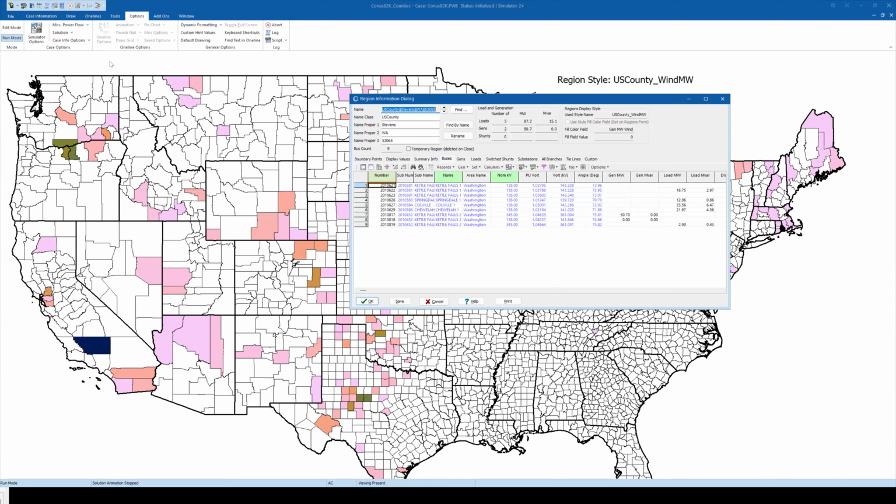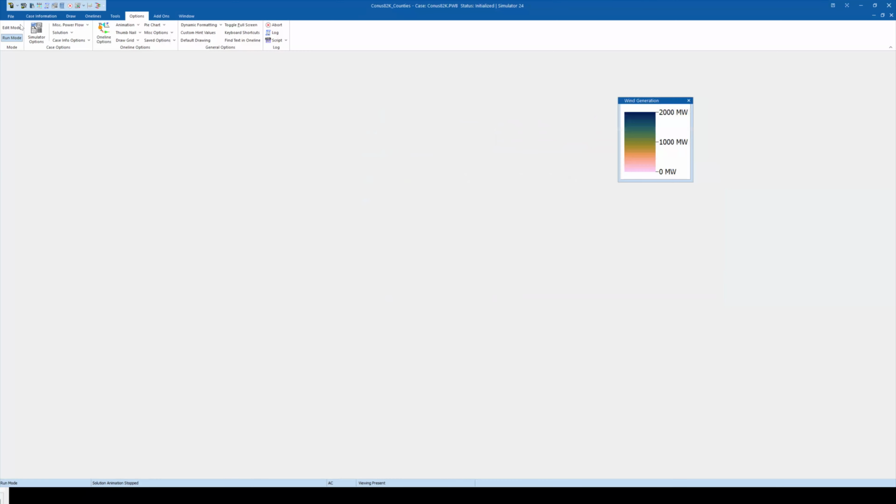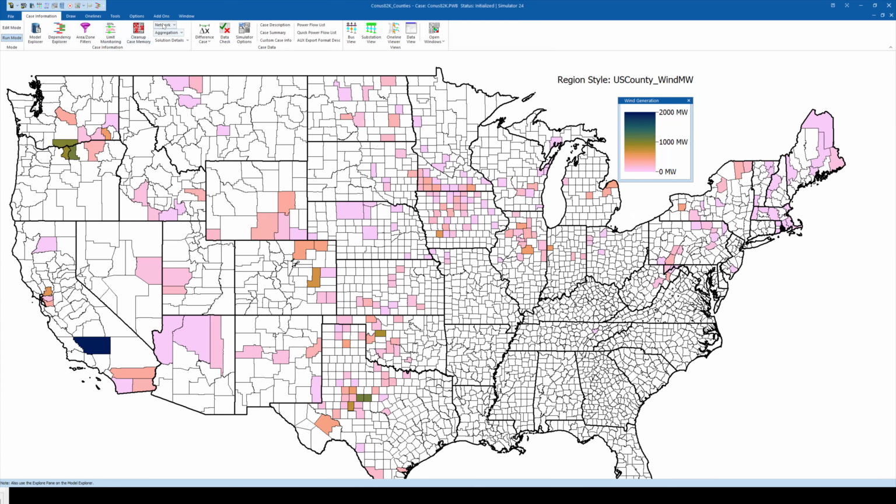Next question deals with whether region attributes can be plotted in transient stability plots. For example, the worst frequency in a region in an under frequency load shedding study. So I'm assuming what you mean, Zachary, is you have a transient contingency, and you want to use the region as an aggregate for the frequency field, or some field like that.